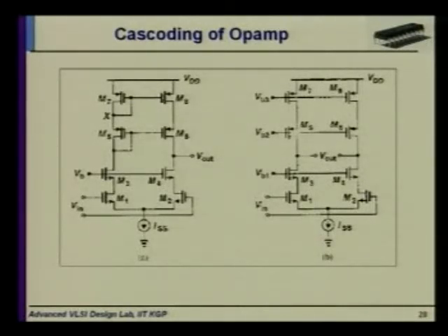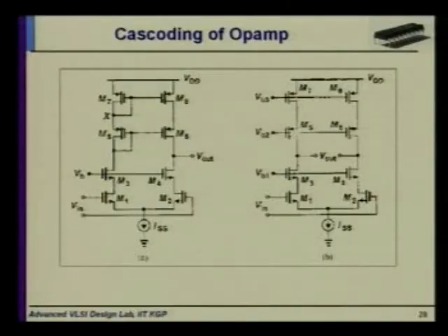But the basic thing is that in an NMOS diffamp, there is a basic limitation: the lower range of operation is limited by 0.8 volt or something like that. Below that value we can't sense. So in that case we need to use a PMOS diffamp, and if we use both of them together, we can have a long range from 0.1 to 1.6 volt, long enough to sense any voltage between 0 and VDD. Got it? This is the overall view of any type of op amp.